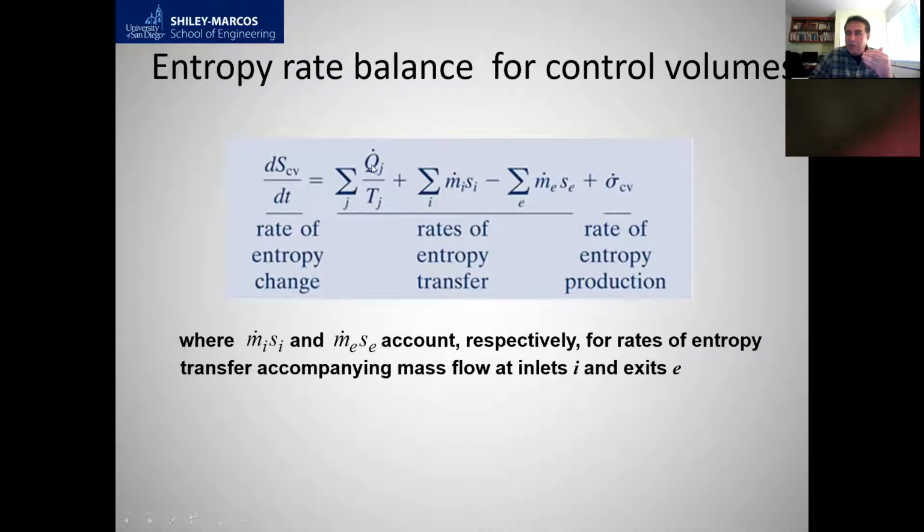Q over T, or Q dot over T. It's a heat transfer rate over temperature. And it depends on the amount of energy that is entering the system. It's a summation, but we just have one going in, one going out, okay, in and out. It's a summation here, no problem. That's the rules. It's the language of mathematics, summation notation. And then j means the first rate, second rate, third rate, and so on.